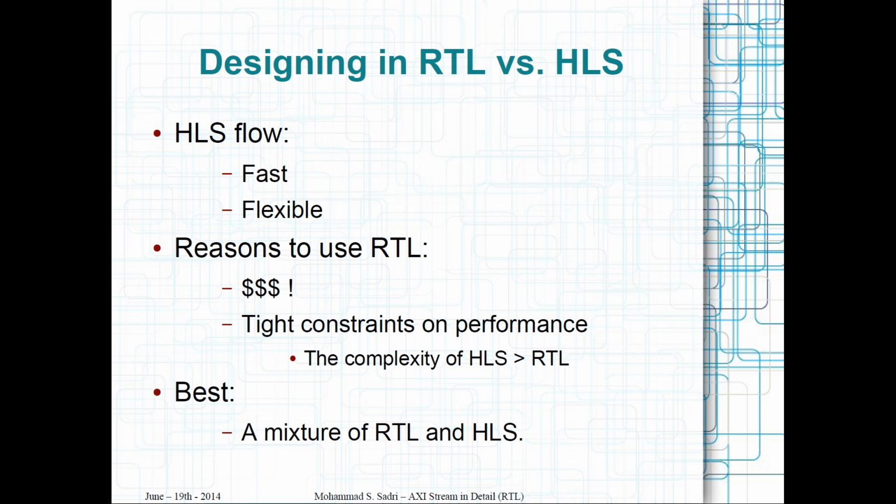Looking at the old days of designing programs for computers, sometimes you preferred to directly code in assembly instead of writing C code, because for some specific portions of the code you wanted to have everything completely under your control. And this is again the story with RTL and HLS. When you are using the HLS flow, in fact, you have one conversion level between the code that you are writing and the logic that is being created.